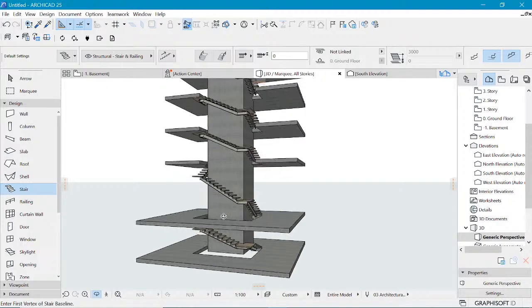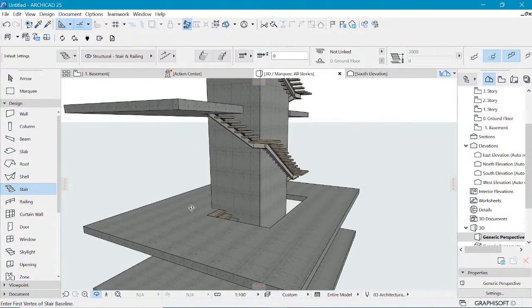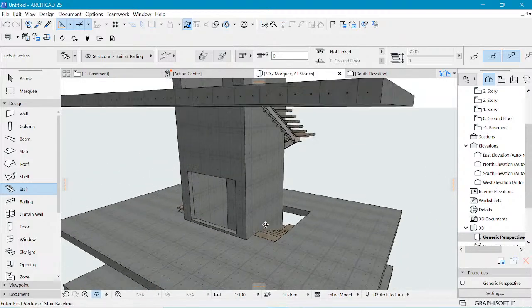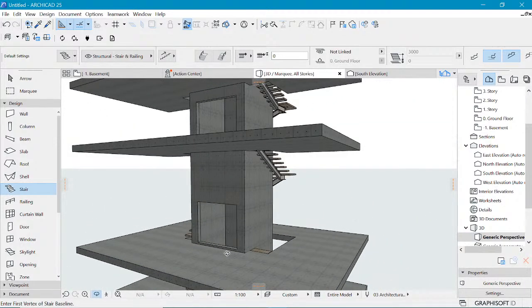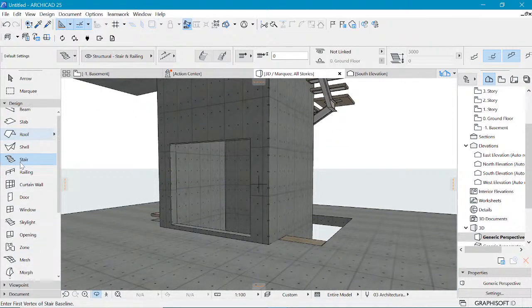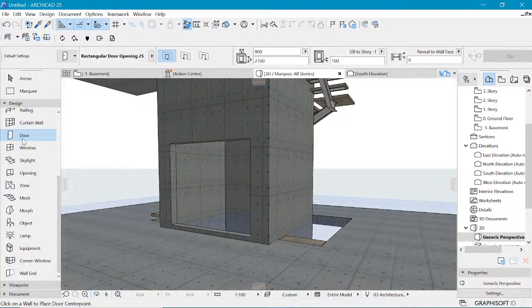So you can already see that we have a basement which you can go through from here. And to remove this, we can select all those openings, which are the empty openings. Let's pick all those. So this is an easy way to do it. You just click on the door icon, then say Ctrl A to have all the doors selected, and then you can add in 0 in order to have that in there.